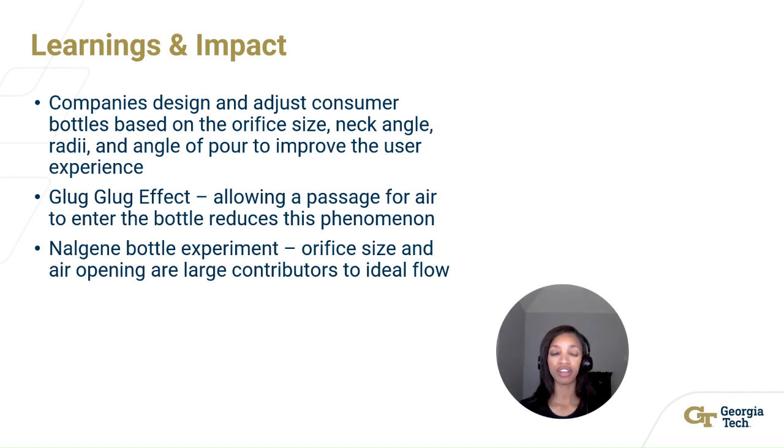Through background research and a few experiments, this project allowed our team to have really great learnings about how fluid properties affect consumer bottle design. In summary, bottles are designed based on the content or the fluid contained inside the container, and companies are interested in designing and updating bottles in order to control the flow of the product inside the bottle, which in turn enhances the user experience.